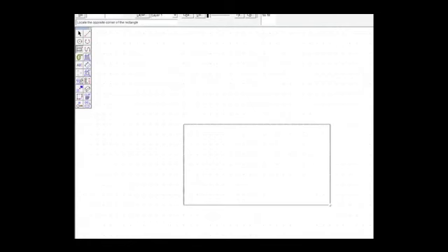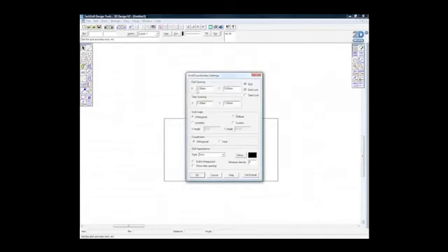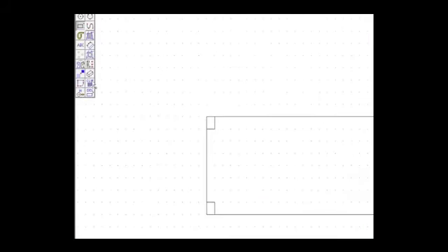and this is the bit that joins all the bits together. Okay, so we've got the square. We're just going to show you quickly how you can trim the edges to make the slots. Okay, we've set gridlock to 3.5 and 5, so we can simply click small squares into the corner to have the bits that we want deleted.